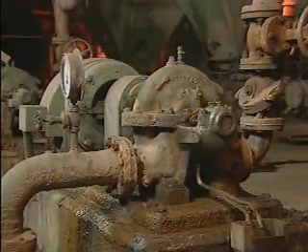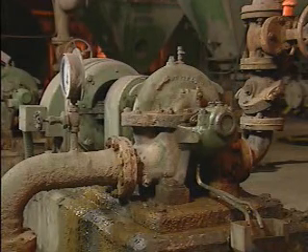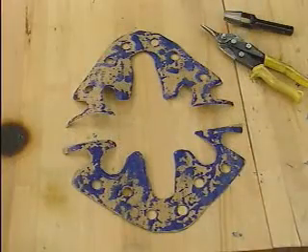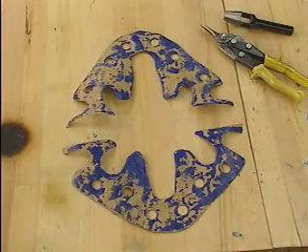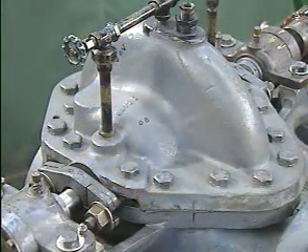For example, the casing for this low-pressure cold water pump is sealed with a flat paper gasket. This economical gasket has a low pressure rating and is not suited to high temperature situations. It's well matched to this low temperature, low pressure application.